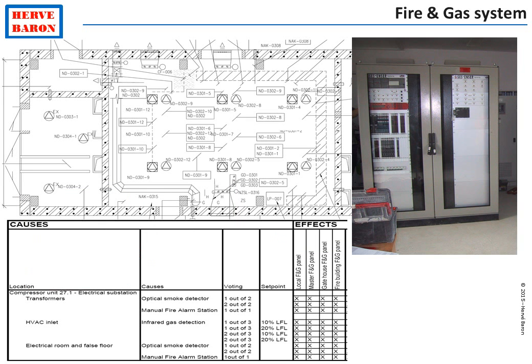The fire and gas system is defined by safety, as we have seen. Safety defines the number and location of fire and gas detectors, as well as their logic of operation, shown on the cause and effect. And the system is purchased and programmed according to these two documents.